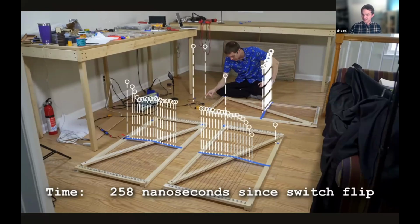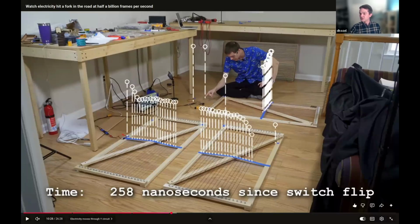And if I hit continue here, we can start to see already in this trace, I'll use my mouse, the voltages come in, it's split off, and it's an equal voltage dividing either direction. We have an equal voltage divider. And as it's hit the short, the voltage is forced down to 0. If you've connected two wires together, the voltage can never be different.